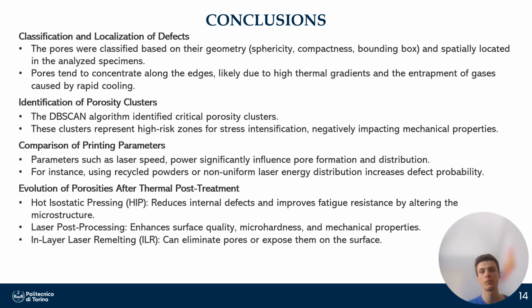The most relevant thermal treatments in this field are isostatic pressing, which reduces internal defects and changes fatigue resistance by modifying the microstructure; laser post-processing, which improves surface quality, microhardness, and overall mechanical properties; and finally in-layer laser remelting, which can eliminate pores or bring them to the surface of the specimen.